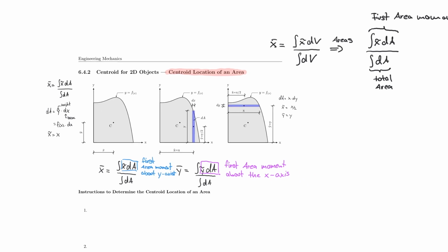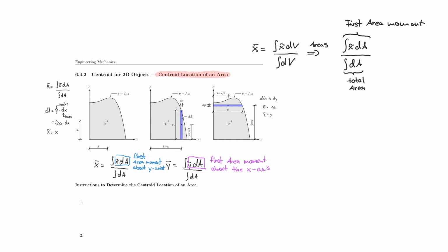So we now brought down the actual formula for the centroid location of an area. And here we're doing dA, but ultimately we're actually taking it down to dx. I will now give you more instruction on how to do that, but please note that we're actually not integrating over dA. I mean, ultimately we're doing that, but we are really numerically integrating over dx.